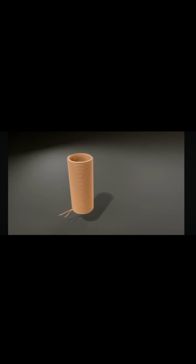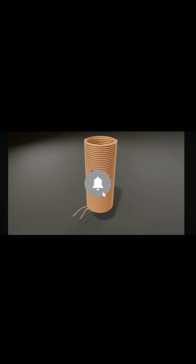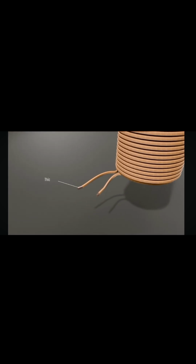The exact voltage and current ratings of the LV and HV winding depends upon the specific transformer. Helical winding is mostly used for low-voltage windings in power transformers. It's the simplest type of winding and is ideal for low-voltage, high-current applications. In a helical winding, the conductor is shaped in the form of a helix. The amount of current in the LV winding of a power transformer can be thousands of amperes, which is why a very thick conductor is used for the LV winding.